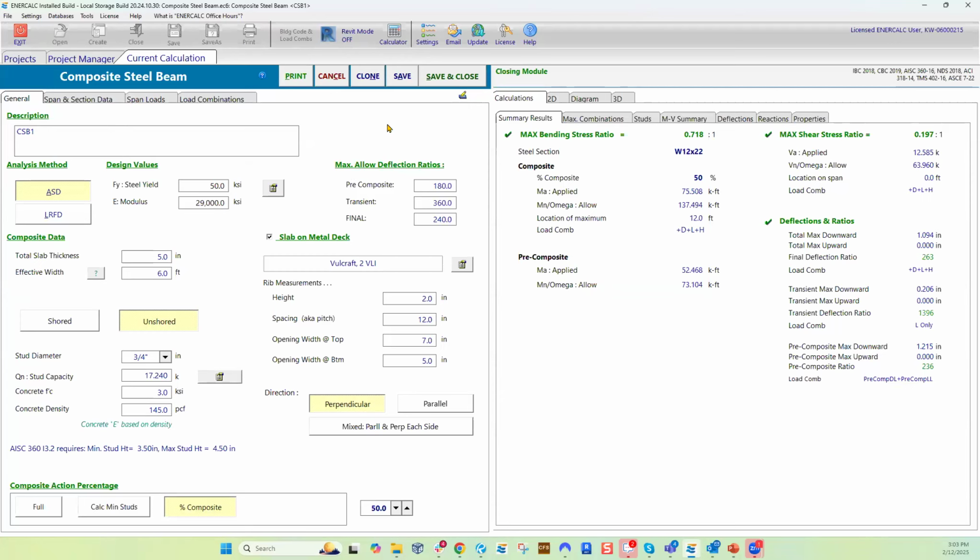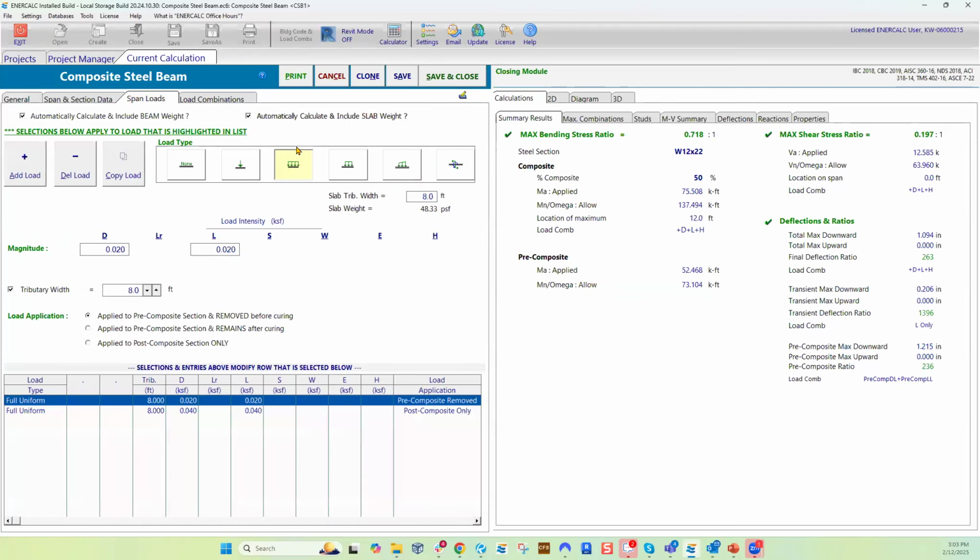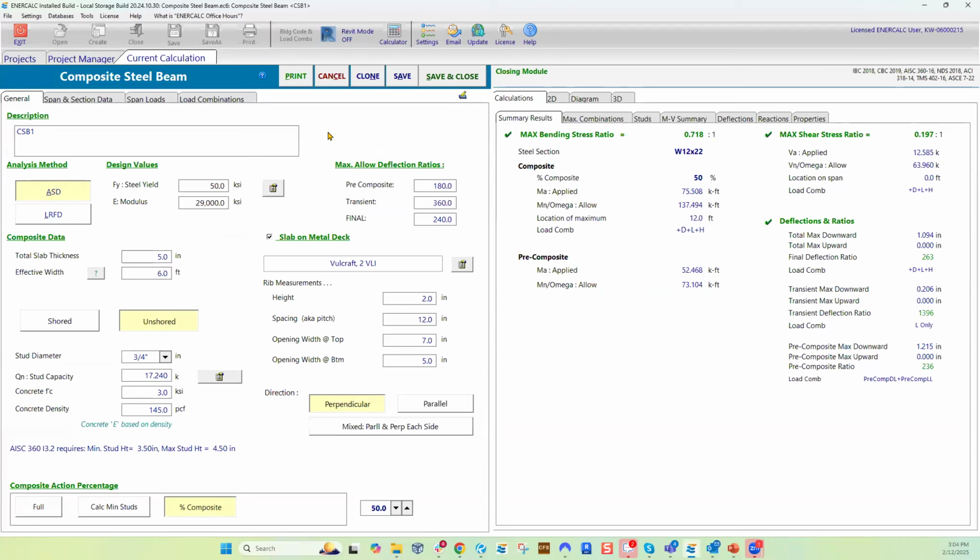Yeah, which is the ponding and all that. But whatever deflection you're getting, this is the part that I want to focus on. Whatever deflection you're getting by adding at least the standard self weight of slab, that deflection is actually permanent. So you'll have it in the beginning and it doesn't go away. And then once you add the other post-composite loads, it's actually additive to it. So we're at least accounting for that. But if there are any additional deflections due to ponding or wet effects of concrete, then that's not included here. Does that make sense what I'm trying to say? Yeah, for sure.